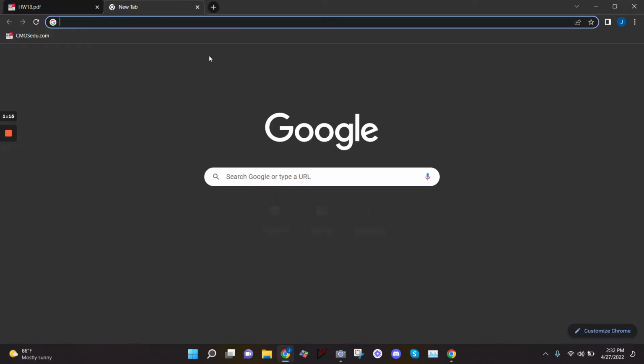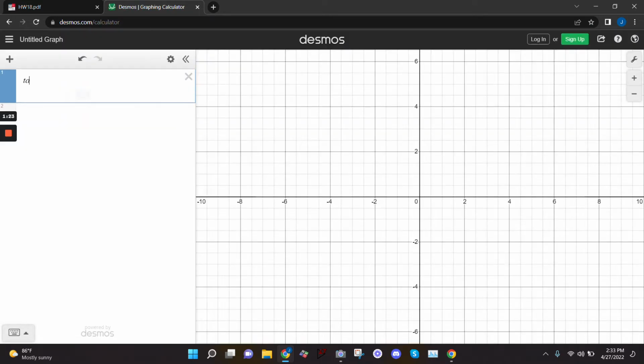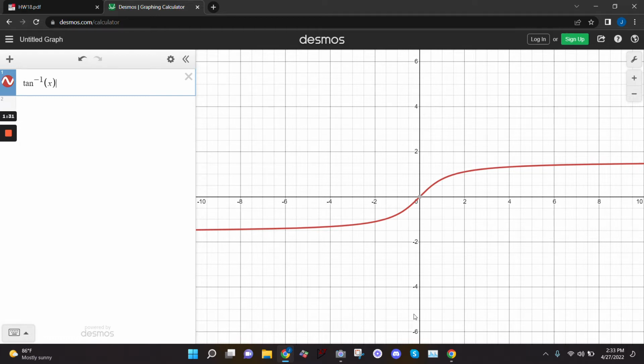One thing I wanted to cover, because a lot of people asked about it. So basically the tan inverse function, if I plot it up, it looks like this, okay? And when you do the phase, you're using the tan inverse of the imaginary over the real. So when I have an inductor, it's purely imaginary. There's no real part. So I'm plugging in a positive imaginary number divided by 0, which is like positive infinity, basically.